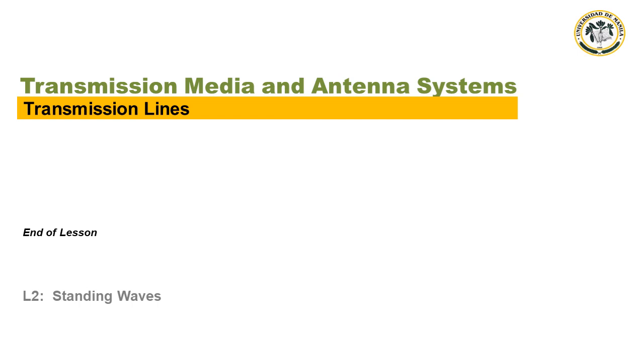However, open and shorted transmission lines are often used to create special effects. We also discussed various ways to calculate the standing wave ratio of a transmission line and define the reflection coefficient. Finally, we learned that the importance of the standing wave ratio is that it gives a relative indication of just how much power is lost in the transmission line and the generator.